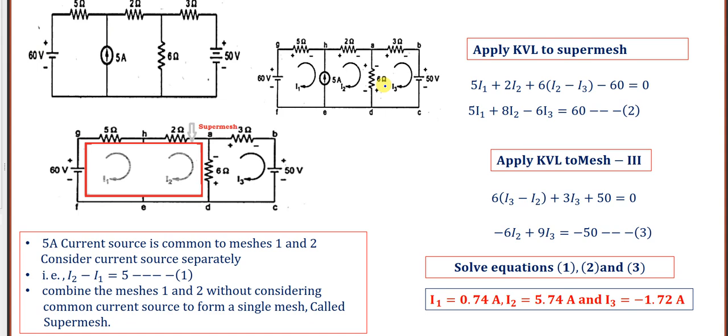Three meshes are there, so three equations are required. Out of the three, I can apply KVL for mesh 3 because voltage source is there, resistance is there. So only one equation I can write here, but another two equations are required. If you have a problem like this, then the solution is you have to combine two meshes. A super mesh is one which is formed by combining two meshes sharing a common current source.